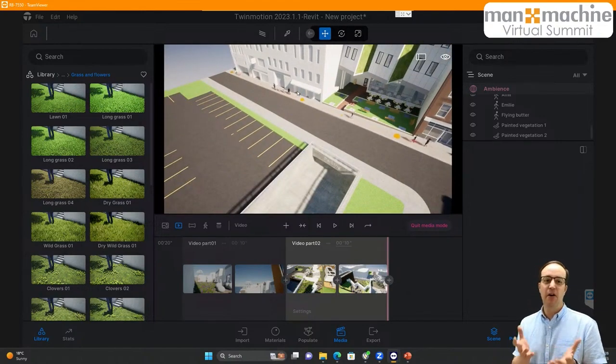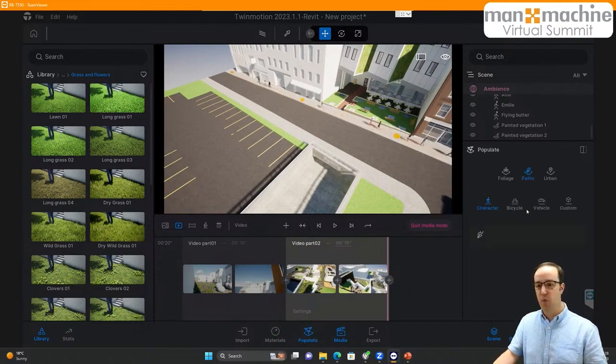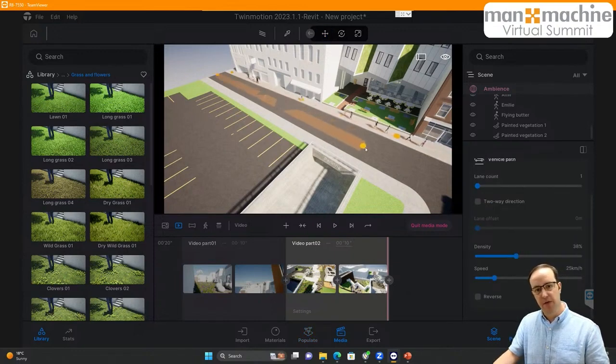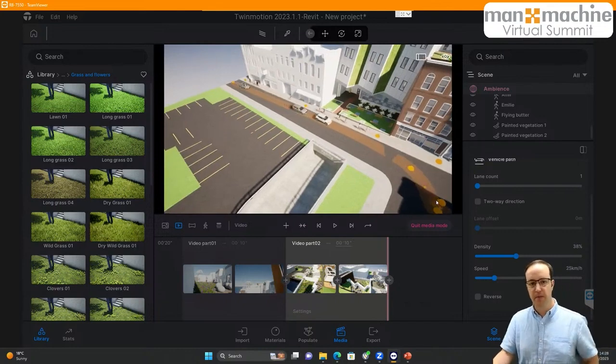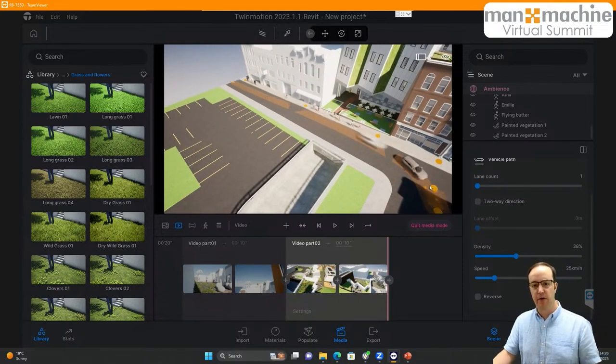But again, how good is that? With your Revit subscription, I can render, I can add texture, and I can add context, as simple as that. Let's do one more. Path, vehicle path, and I'm going to click a few times down this road. Maybe we'll try and zoom out a little bit and turn a corner just because we can. Right click to confirm. We have vehicles driving down the road.